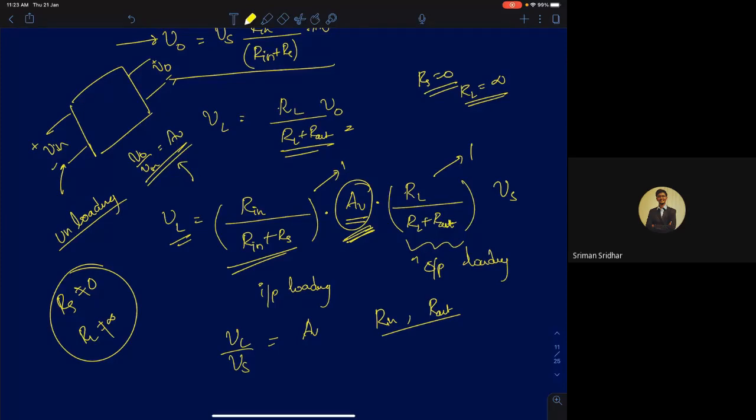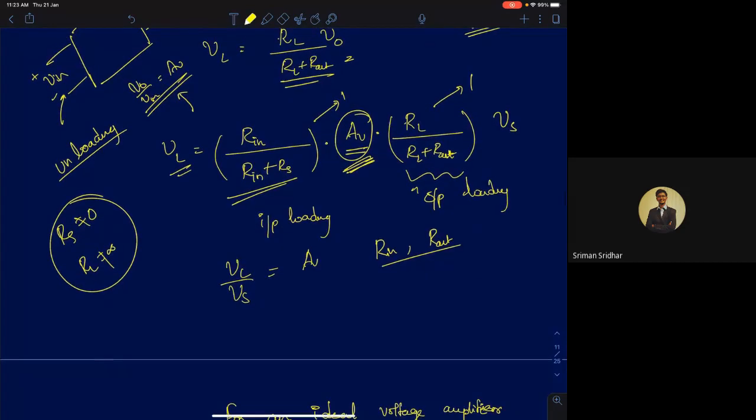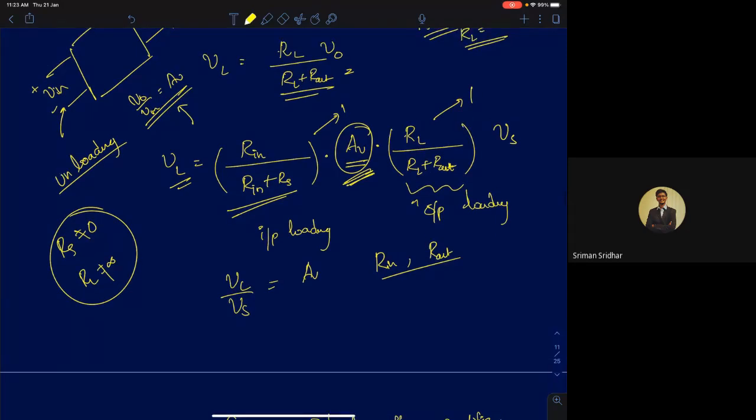Okay, so now I'm just asking you guys, can Rout be... it's not a gain, infinite resistance. I think you're asking about infinite resistance. Yeah. So I'm just theoretically asking you, as an engineer, if your goal is to get maximum voltage gain out of a voltage amplifier, then you will choose Rin to be infinity.